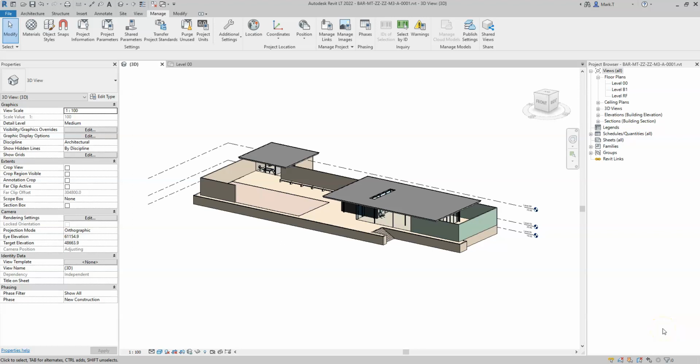Now that we've covered the spatial elements within the IFC export, such as the IFC spaces and IFC zones, we'll now look at actual building elements. Unfortunately, Revit's inbuilt categories do not align to the IFC classes for building elements, nor can they be amended, added to, or deleted.